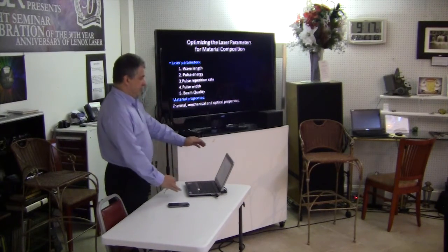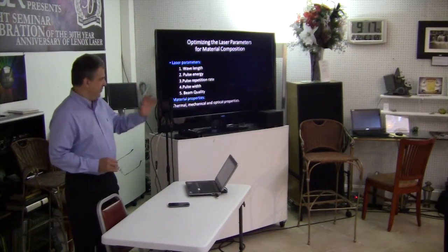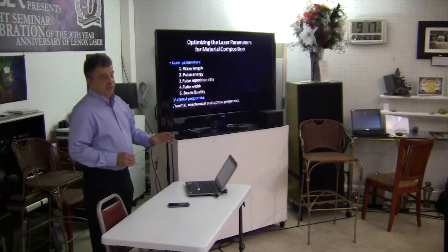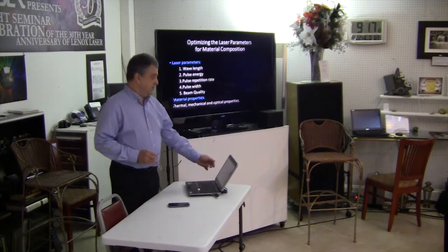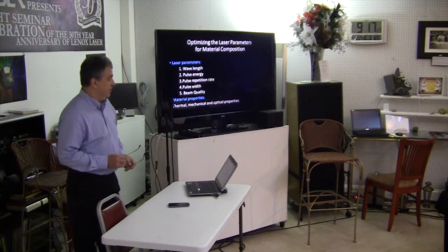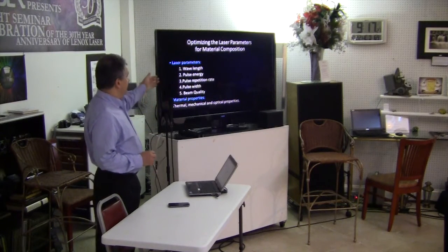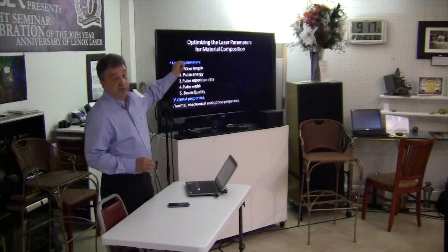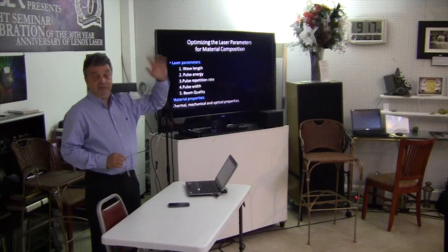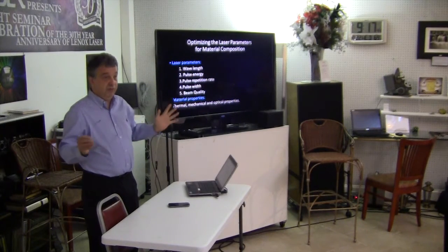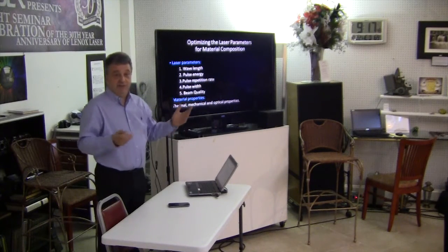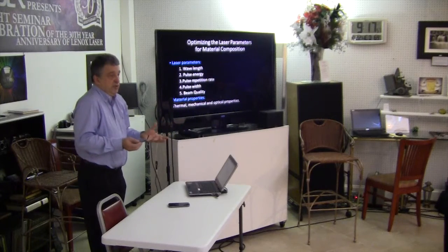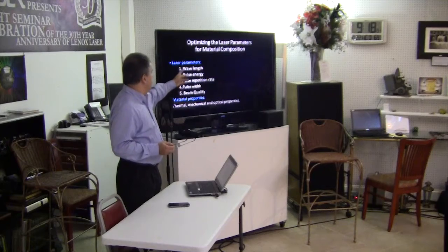And to do that, we need to optimize certain parameters of the lasers. So we're dealing with two different things: the lasers and the materials. And in the lasers, there are not so many parameters to optimize, like wavelengths, pulse energy, pulse rep rate, pulse widths, beam quality. And wavelengths determines the color of the laser and determines the absorption of the material that you have. So any material lacks certain wavelengths. Like for example, if you just shine the light through a piece of glass, the green light, it just goes through. It's not being absorbed. So presumably, if you measure the energy before and after, that piece of glass does nothing to the light, unless you try to delay it and so forth. We want the material to absorb the light, so we want that laser beam to do something, so energy has to be transferred there. And in this case, wavelengths is very important.